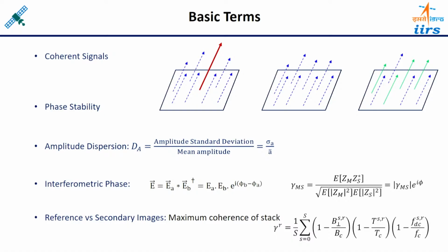Okay, so within this resolution cell two types of scatterers are there. One category of scatterers is responding moderately, and another category of scatterers is responding very strongly. Such kinds of pixels, or resolution cells, are called persistent scatterers. The point is, whatever the red color response is, it means there is a very strong target which is responding in all the signals. Suppose one image is acquired at time t1, another image is acquired at time t2, t3 and so on.